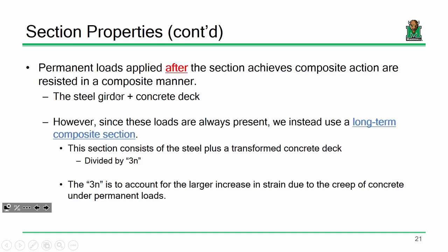Now, here's where I want to take a little bit of time. Remember that I was talking about those permanent loads that are applied after the deck cures, things like the barrier, bituminous overlay, future wearing surface, utilities, things like that. They're on the bridge all the time. Okay? They're not going anywhere. Now, if you've had prestressed concrete, you know as well as I do that concrete is a material whose properties change over time. Concrete undergoes things like creep and shrinkage and what have you. Because of that, concrete's properties not only change over time, but they get a little bit weaker.